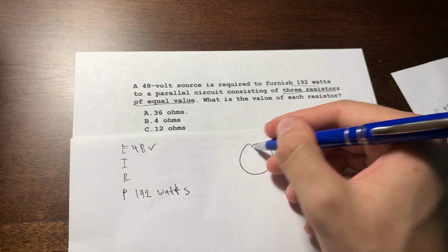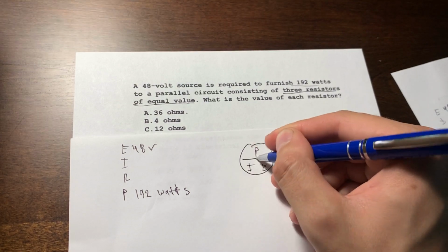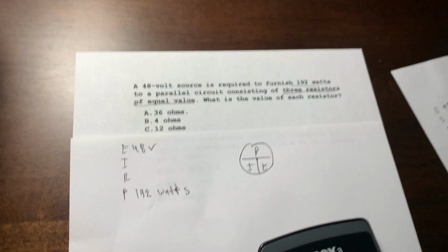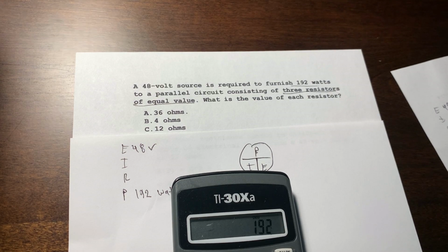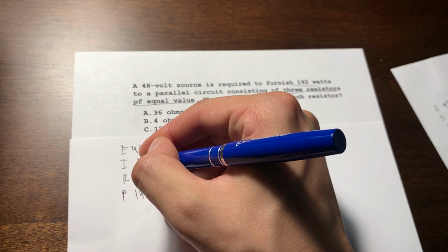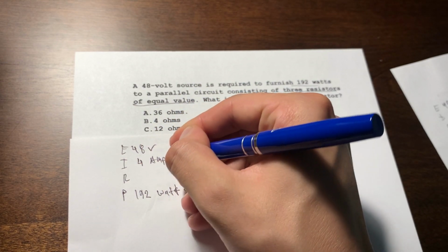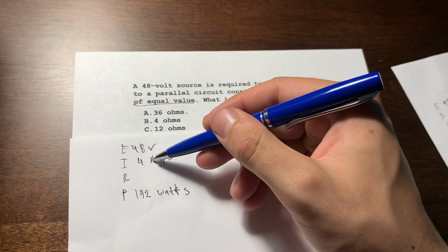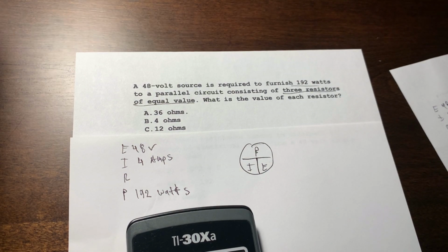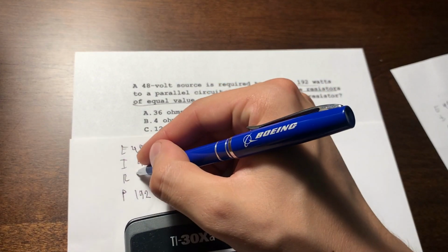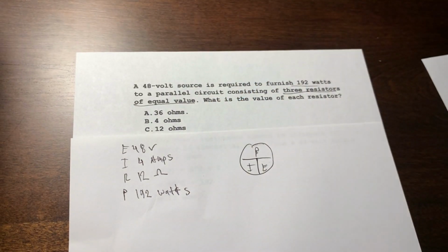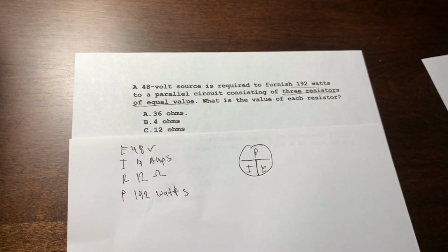So using Ohm's law, P divided by E gives you current. So 192 divided by 48 gives us 4 amps of current. Now that we have E and we have I, we can calculate R. E divided by I, 48 divided by 4, 12 ohms. So if you got 12 ohms and you clicked 12 ohms and thought that was the answer,